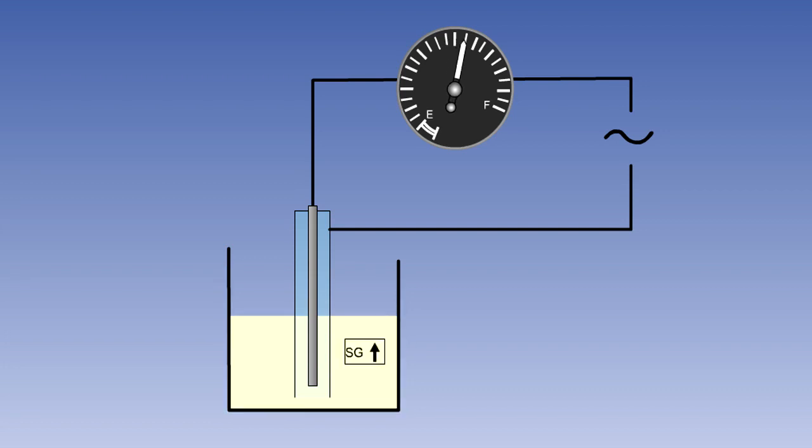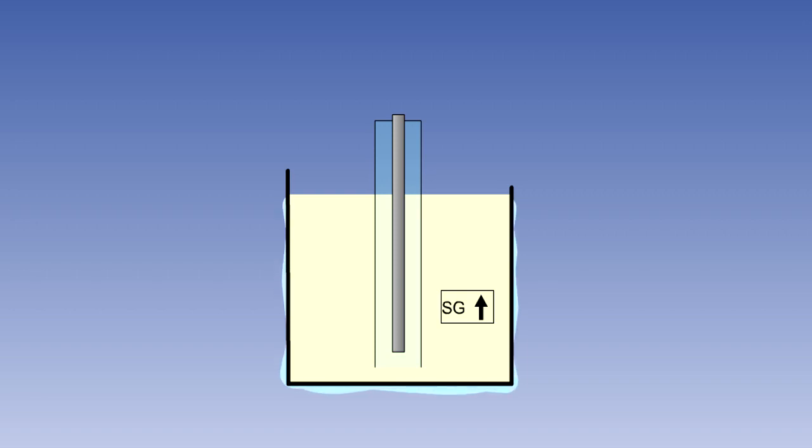The dielectric constant of fuel changes when its specific gravity changes. If the specific gravity of the fuel increases, more current will be allowed to flow in the circuit, and similarly, if the specific gravity decreases, the current flow will decrease. When the volume of a fuel reduces because of a reducing temperature, its specific gravity increases, and vice versa when the temperature increases. The system is designed so that these two changes cancel each other out. The capacitor type of system is therefore able to measure the mass rather than the volume of fuel. There is, however, still the problem of attitude error.